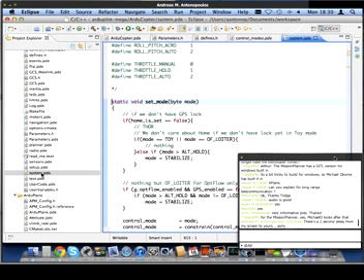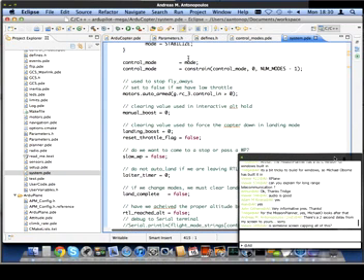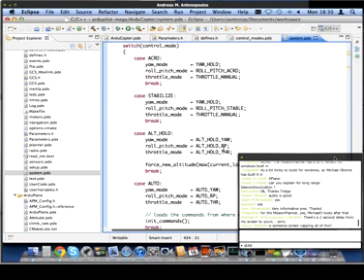Set mode, you'll find, is in system.pde, line 415. You can see it's got one parameter there, which is the mode, so that would be something like, for example, stabilize. If you go down a little bit more, just keep on going down. Yeah, so it's setting the control mode to the mode that you've passed in. And then right here, this is the important bit, this big switch statement.